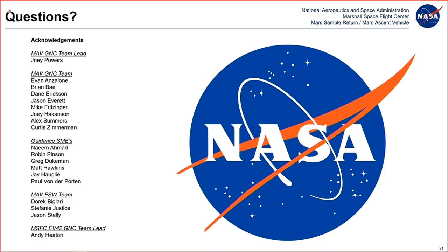Okay, here's another question. When the second stage is targeting a specific target orbit, why doesn't it just target the highest orbit it can reach? For a sample return mission, wouldn't that reduce the delta V cost of the pickup vehicle, which comes and picks up the sample? It's a good question, but no, it actually doesn't. The reason we're targeting a specific semi-major axis rather than the highest one, if you remember from orbital dynamics class, is that the rate at which your orbit precesses because of J2 is dependent on your semi-major axis.